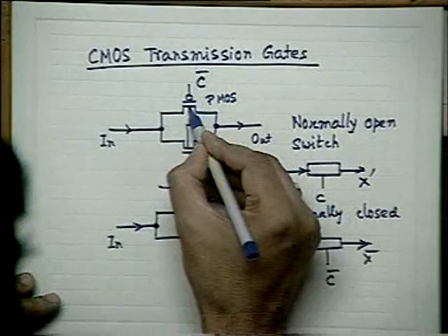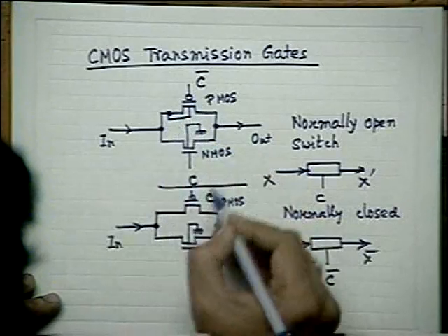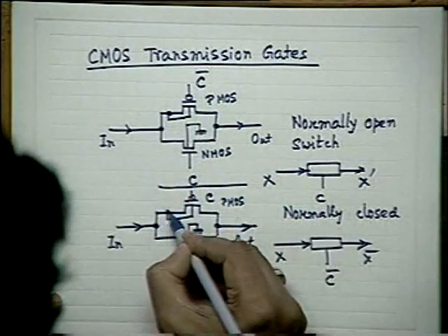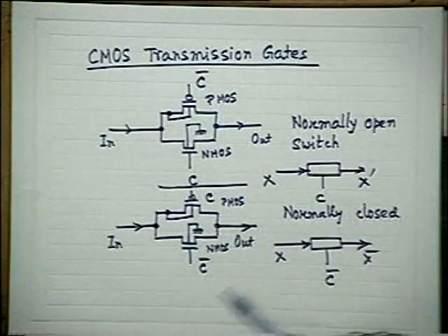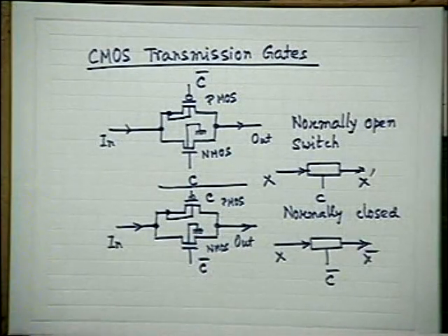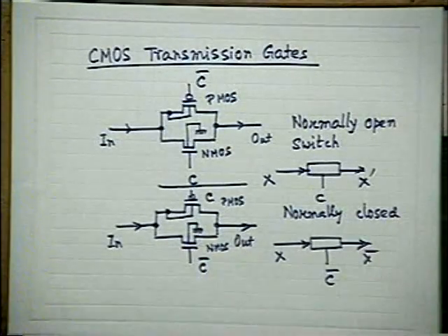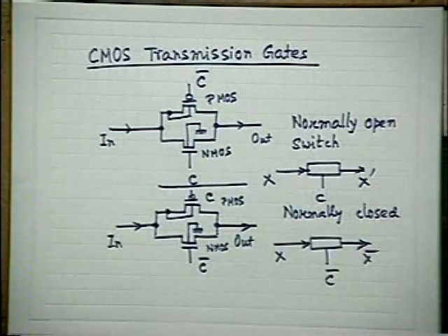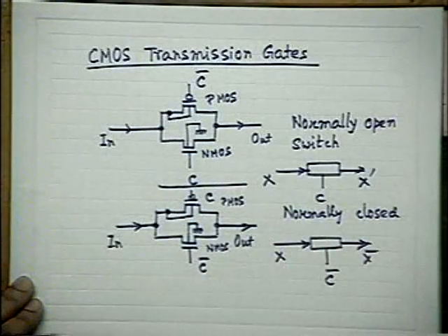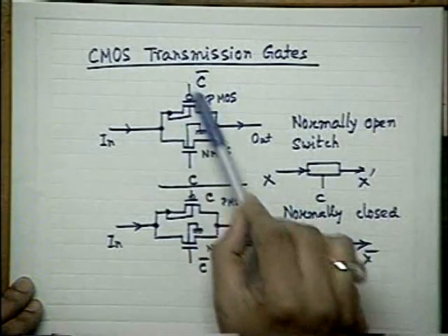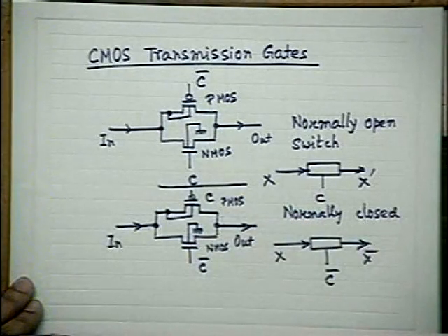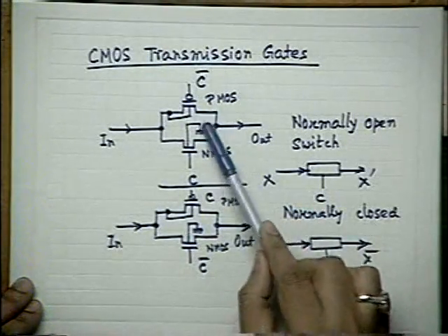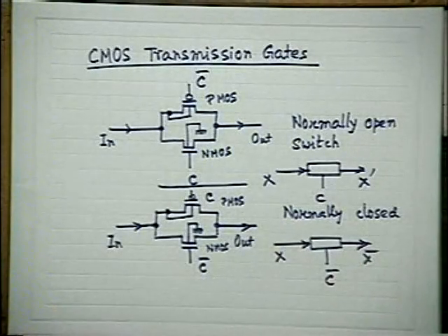You just see that in this case, I think I have done this one. PMOS in this, these are floating on N wells. In this case, this side is always behaving as the source side, whereas in the other case, this side is behaving as the drain side. And that's normally the case for normal CMOS.